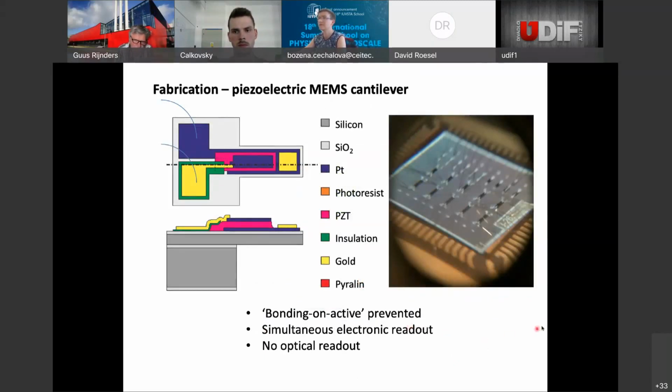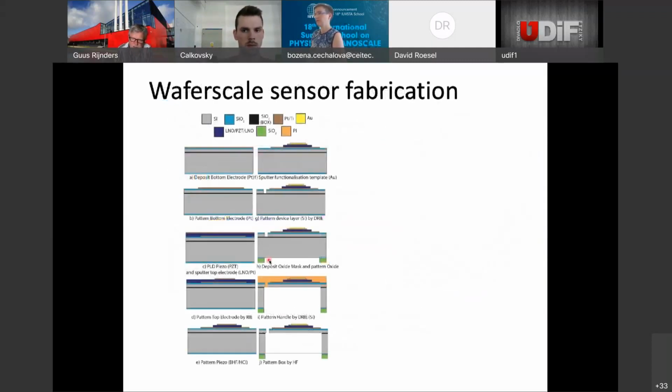We used this piezo MEMS technology. Here you see the chip completely made, where you have this silicon membrane, and on top of that, this piezo capacitor, and you can make it vibrate, and with that you can measure the mass. It's like a mass sensor. And here you can see